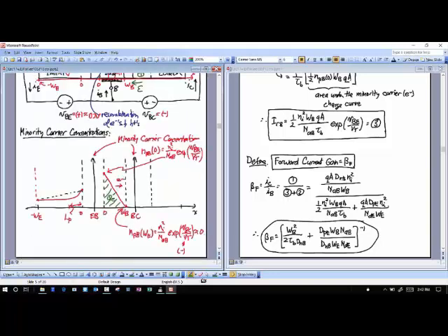And so let me also complete this picture here. What do you think the minority carrier distribution looks like in the collector? What does it have to be at this point here? Or sorry, I already pointed at it, so it's right there, right? Because I've got a reverse bias across the collector-base junction. But out here, it's going to be somewhere around there, which is going to be the equilibrium concentration, not current, but charge concentration, right? That's the whole concentration gradient in this. And so, in the end, it'll look like that. Okay, just to finish the current distributions that I have in all of these things.